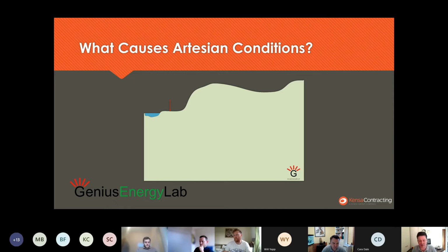so hopefully it'll give you a better understanding of what we're talking about here. So let's imagine we're going to be drilling a borehole here. This is maybe Sheffield or somewhere in amongst the hills, and we've got a river to the side there. So the first thing that you might think of is, well, am I going to have a problem with the river? So is there maybe a bed of gravel or something like that under the surface here I'm going to be drilling through, that's going to be full of water? Is that going to be a source of potential Artesian conditions?